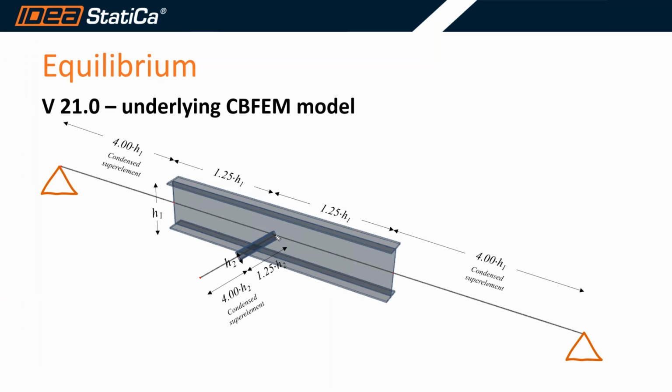So in the previous version, we were using multi-point constraints. So if for example, you wanted to have a shear force at this point, we were using the constraints to constrain the end and transfer the load there. This is roughly it, okay? Now these constraints were preventing this from deforming. So in the new version, we're using the super elements to move the loads. And that way, this allows the member end to deform freely. This is roughly the theory of it.